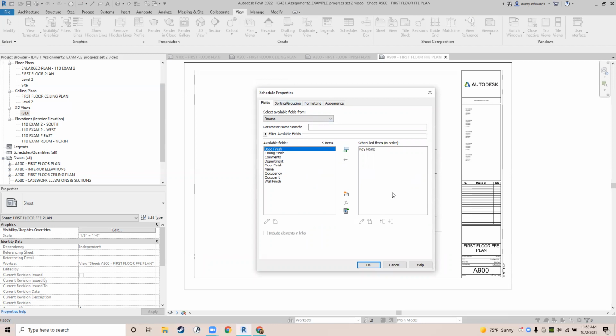So Revit can smart schedule things to where it can automatically count all of the doors. It can organize the doors by type, by size, by room. It can do all these great things on its own. It just knows how to count all these model components, but we're not really going to be counting model components for the FF&E schedule. Instead, we're going to create a dummy schedule.